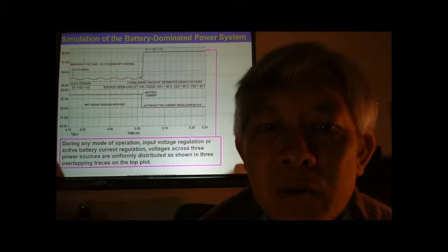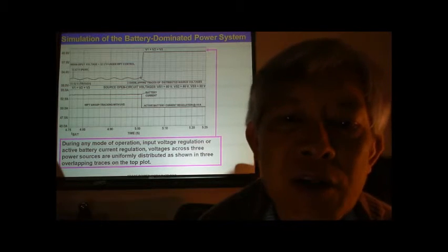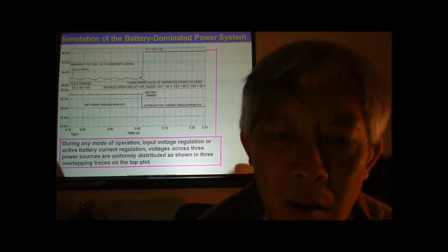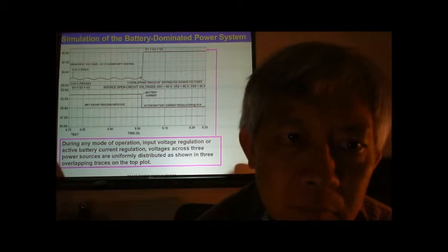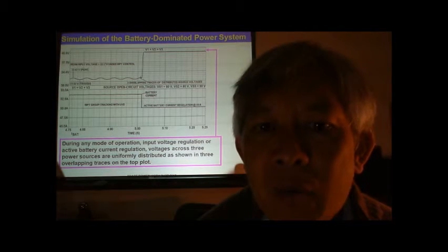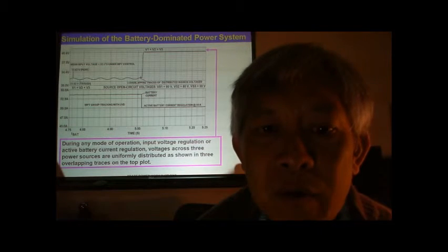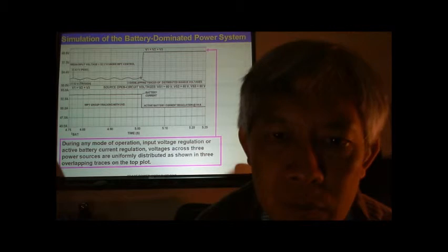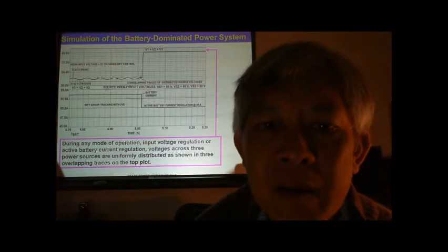The battery controller has already lost regulation because its charging command is set significantly high, above 53 amp. As soon as the battery controller reduces the charge command to 50 amp, the battery charge controller is able to restore its control and cause the maximum power tracking mode to be in standby mode.